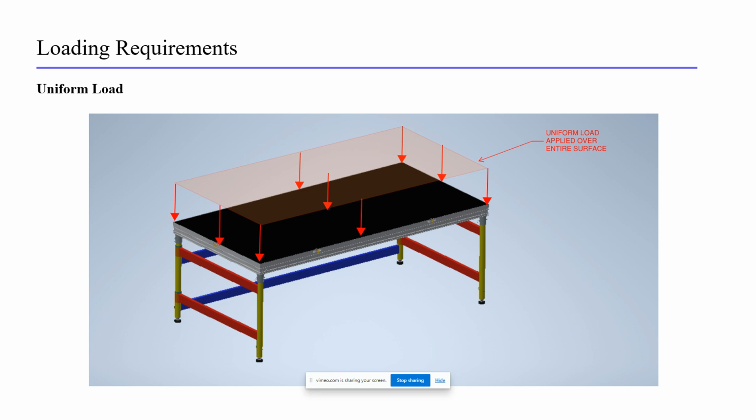Let's talk about the loading requirements. Generally, as you're all somewhat familiar with, loading requirements are the forces that are required to be applied to structures. They come from gravity loads, dead loads or self-weight, human activity that we call live loads, and the environment, such as seismic, wind, snow, and temperature. Live loads almost always determine the construction of demountable systems. Seismic loads can occasionally affect design in high seismic regions, such as California, and wind loads, of course, are present on outdoor structures. Temperature loads are caused by expansion or contraction of the system. They may need to be considered in certain exterior installations.